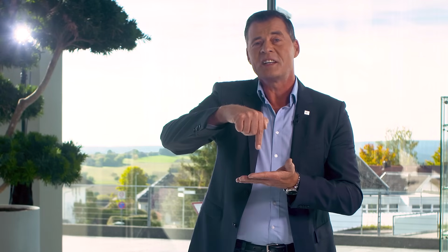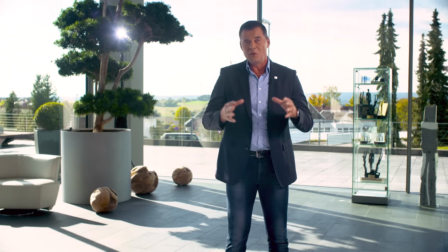I still come from the generation when CNC machines were programmed in DIN 66025. At that time, every single processing step had to be programmed in a complex way. Many of you may remember this. Commands like G1, X200, Y200, Z10, T81, F3000, M3, etc. Selecting the direction 200 mm Z, the depth, the tool, the feed rate, all of it was laborious.